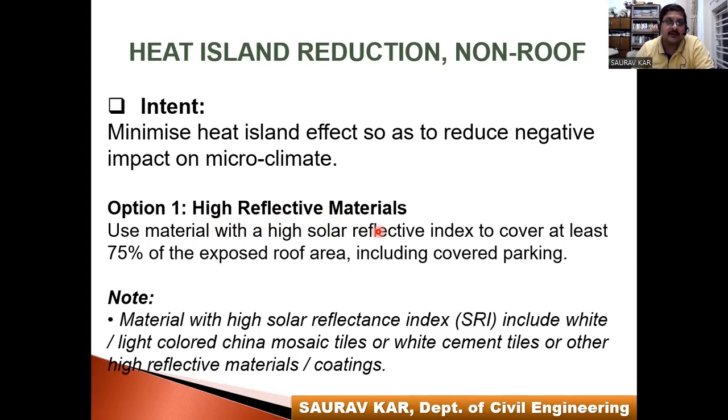We all know from our childhood days, a light colored shirt, a light colored dress reflects heat, while dark colored clothes absorb heat. So it's the same common concept. Use materials with a high solar reflective index. Very important point, very important. Solar reflective index, SRI, to cover at least 75% of the exposed roof area, including covered parking.